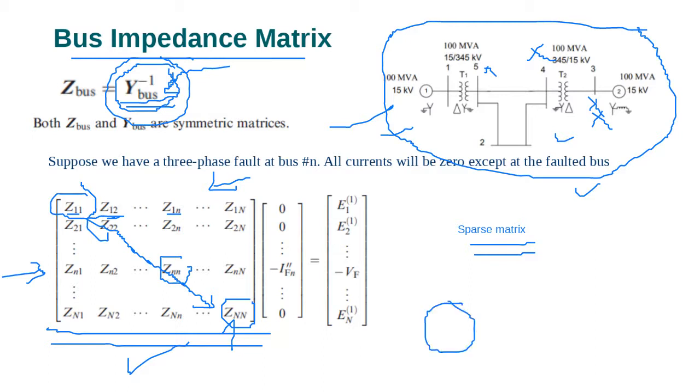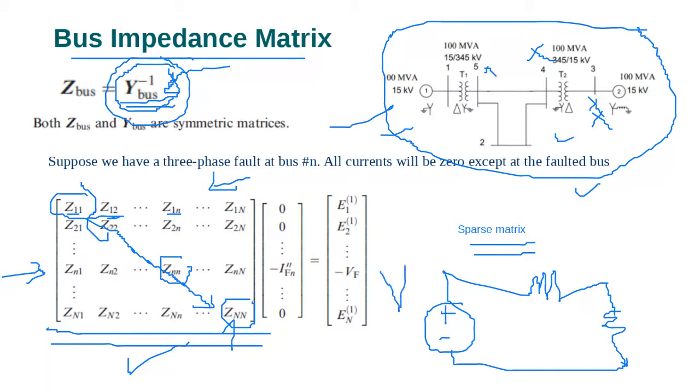Then we have the voltage, and we have the Thevenin impedance here, like this one, and then we have the load. This is the load. You remember now? What will this voltage be at this bus? It is the voltage at the bus where you want to calculate the fault current. So if this is bus number 5, this will be V5. So we look at the bus, see what the voltage of the bus is, and this is the Thevenin impedance. Then we can find the fault current.